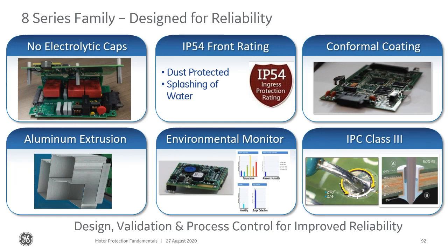The 8 series family of relays, we have designed it so that we don't have any electrolytic capacitors. Electrolytic capacitors were the capacitors that, as they aged, would dry out. This would cause them to fail if they were powered down and then subsequently powered back up. So that was a failure point in our relays that we have eliminated here in the 8 series.